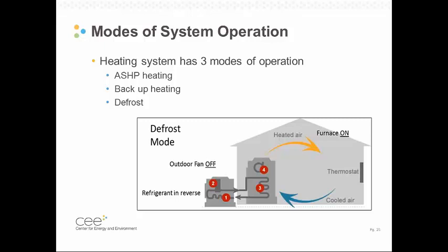The way this is done is purely on a temperature measurement outside. So whenever the conditions are present near the coil for there to be frost buildup, essentially anytime it's below 35 degrees right by that coil, the system will run in reverse, heat up the coil, and then restart the countdown until the temperature drops in there again and the defrost has to run.